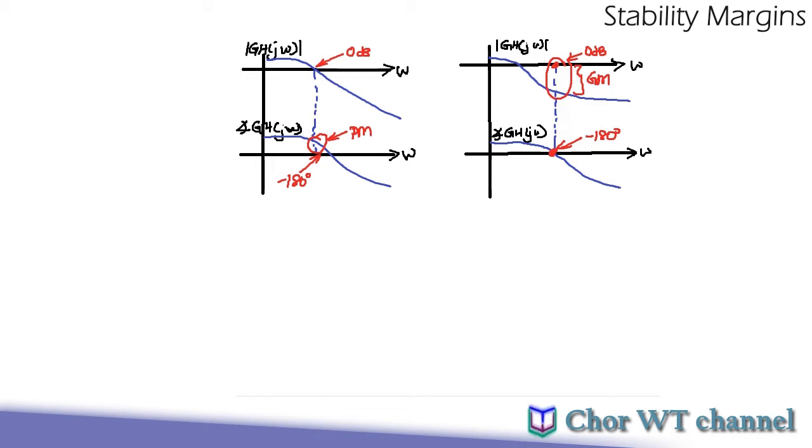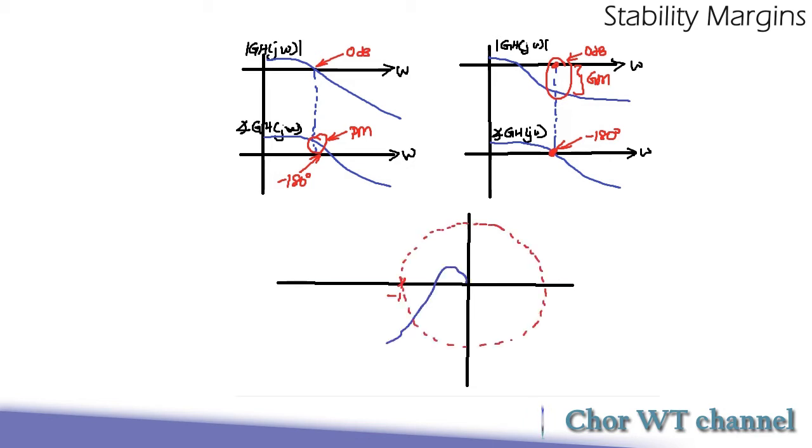Next, we move on to the Nyquist plot. We consider a typical example of the Nyquist plot as follows. Okay, now we have all the information as required. We go back to the same definition where the magnitude is equal to 1, which means this line. Basically, we are focusing on this line as highlighted over here. So this line will form our boundary of stability. We will be observing this point where it crosses at the minus 1 point.